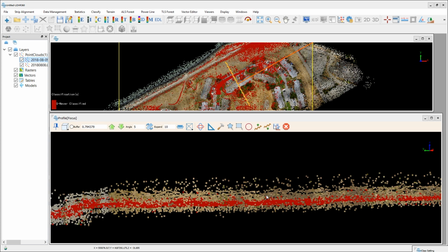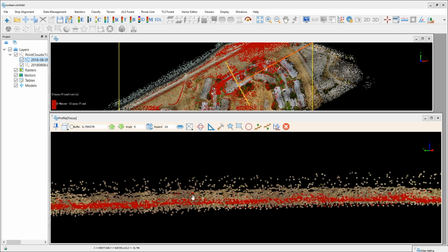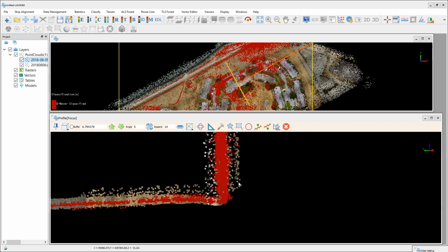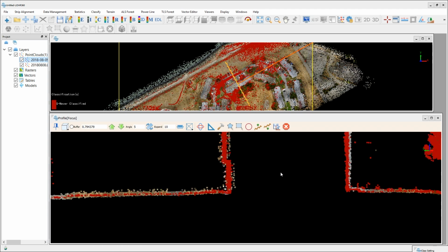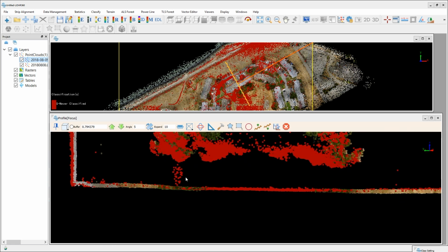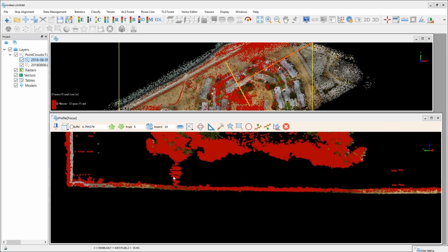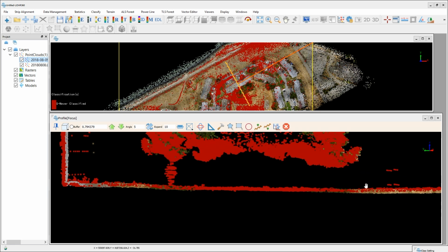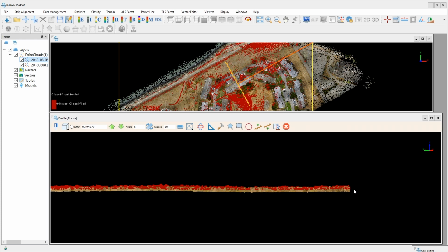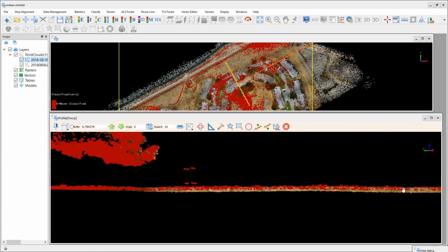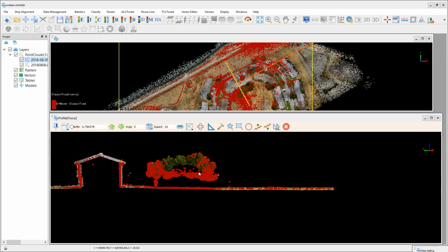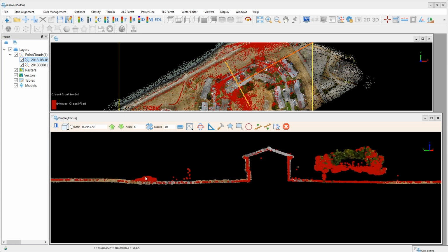What I like is that the UAV LiDAR data set, or the true color points, are somewhat normally distributed about the live backpack data. This means the live backpack data forms sort of a central tendency between the spread of points belonging to the UAV LiDAR. As you move away, you see some drift where the UAV LiDAR does not fit the exact center, the live backpack is not fitted to the exact center, but the alignment is much improved over our first go at it.